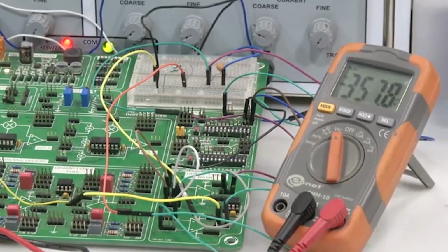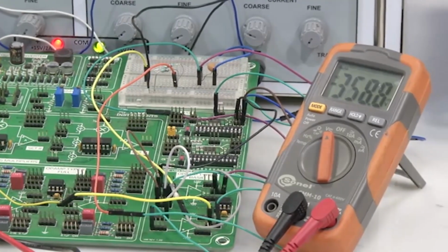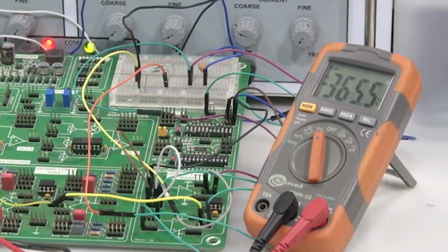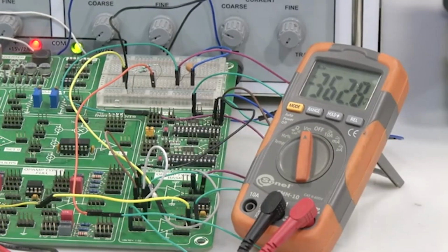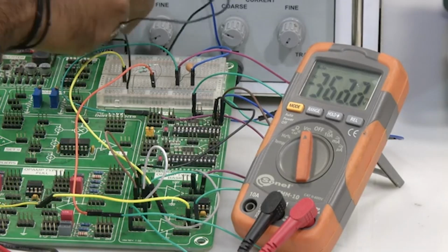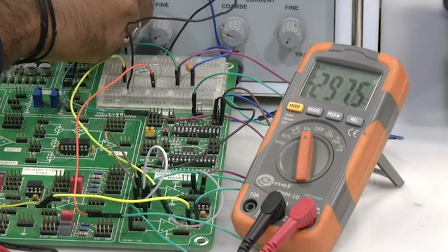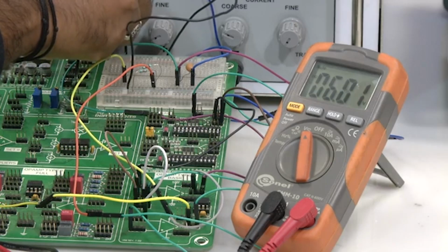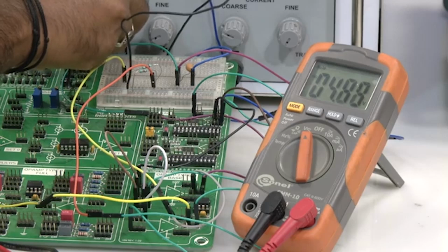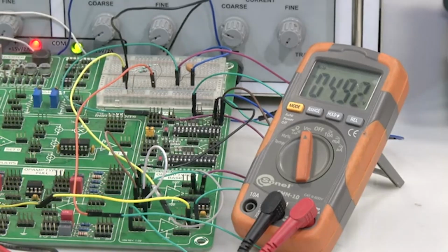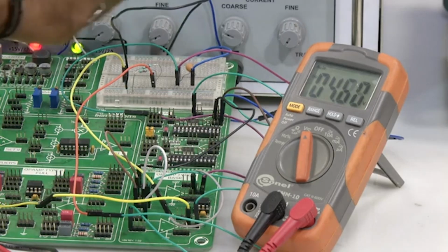One more thing to notice is that when I go beyond 100 millivolt, because we have two stages of op amps here, the input swing should be very minimal. It is used for processing very small input voltages. The moment I go to a high voltage, till 290 millivolt it is okay. Whatever gave 300 millivolt for 50 millivolt input, my input is now 290 millivolt. So accordingly our DC output has become 4.3 volt.